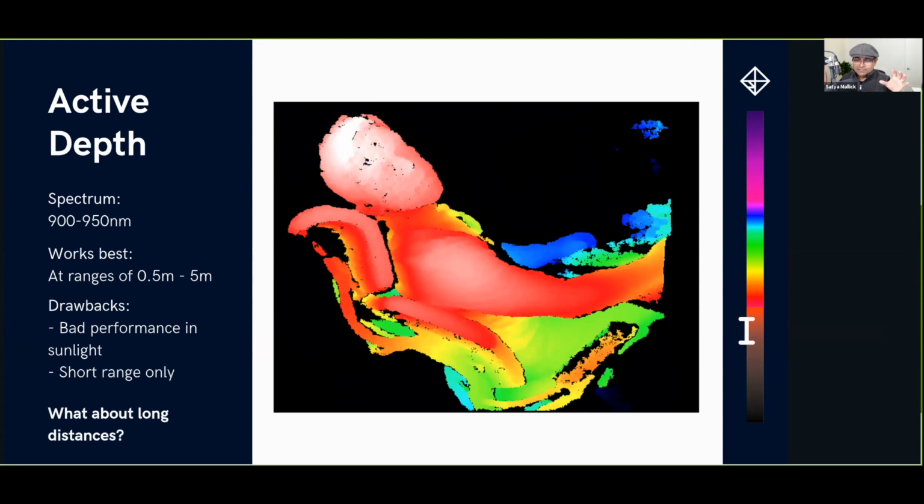They're using the same concept, but instead of using two cameras, you're using a projector which projects a pattern onto the scene, and then you're looking at it through a camera. And since you know what pattern is being projected, you can detect and triangulate. That's right. So that was the standard technique for these sensors.